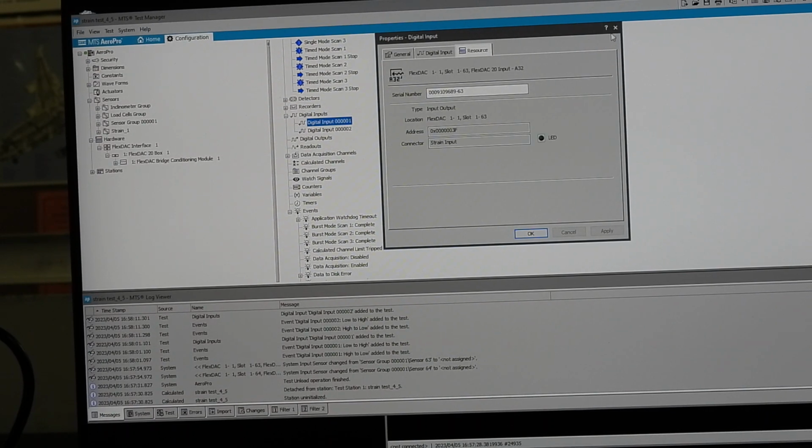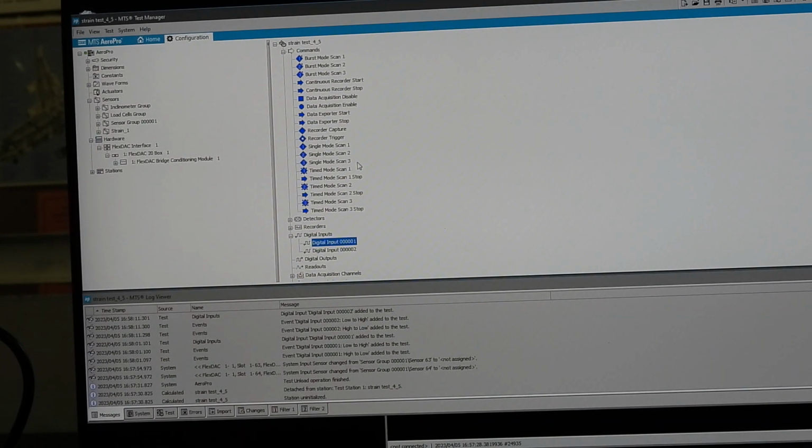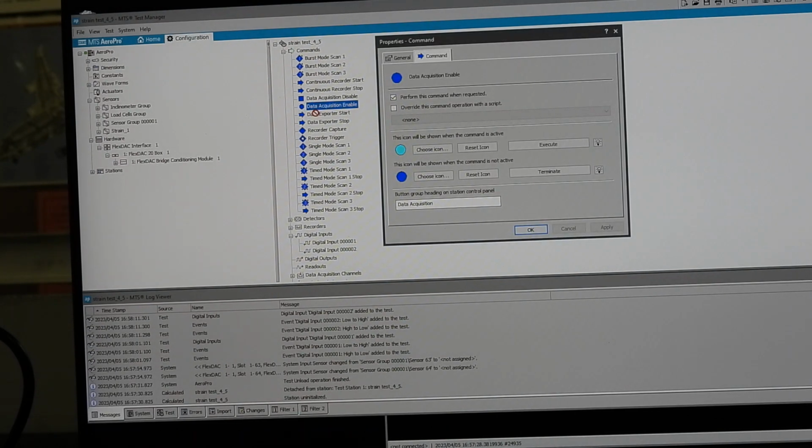I'm going to say the supply current is 20 milliamps at 7 volts DC. But that's what it draws. That's what it's saying it draws. What do we set the voltage as? Excitation 10. Yep. So at 7 volts, 20 milliamps.